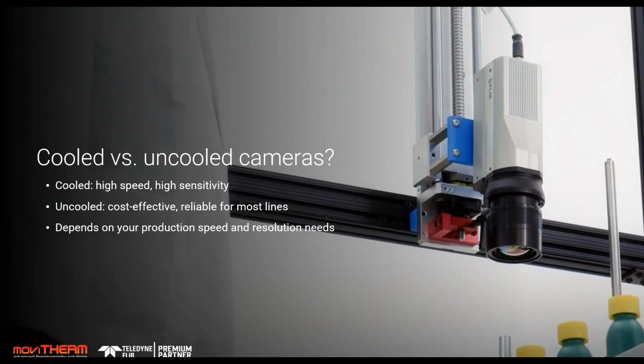Yeah. So, the cooled cameras were the original ones, right? They used liquid nitrogen to cool down the detector. That's why they call them cooled cameras, because when they originally were building these cameras, you needed to have the detector, if you think of a regular camera like a CMOS detector, that's what we're talking about, the focal plane array, cooled down in order for the photons from the infrared spectrum to hit the detector. Back in probably about 1997, Flir first introduced a camera that did not require cooling.